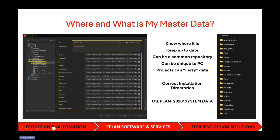So as per our installation guides that we provide when we provide ePlan, you have a directory we suggest you use, especially for 2026, and that's C drive, ePlan, ePlan 2026, system data. And we suggest keeping every year's master data independent, but then copying across what you need to use. And in this way, you won't confuse things like parts databases from previous years, and it will still give you access to previous revisions if you ever do need to.